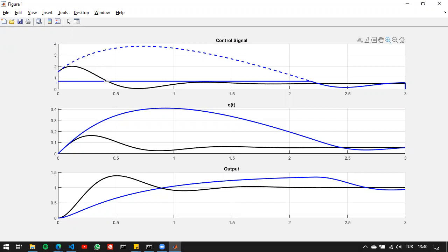At a certain point, even though at exactly this point we don't have to apply values higher than 0.7, we still can't. And the reason here is that the integrator part grew so much that we cannot apply a small control signal.